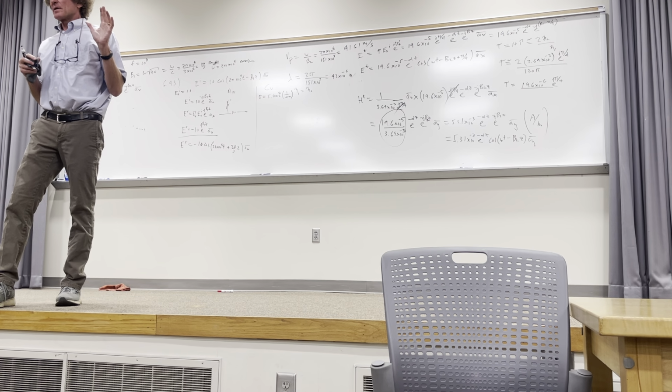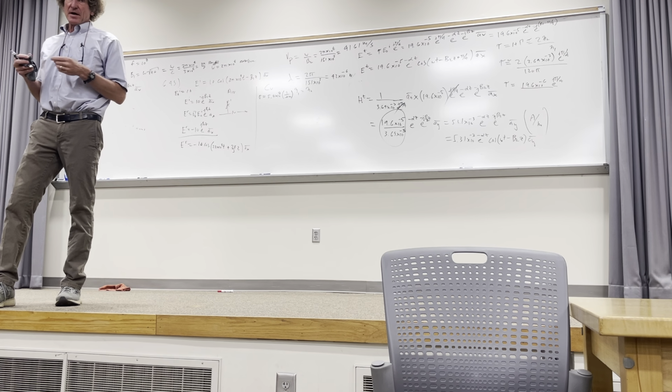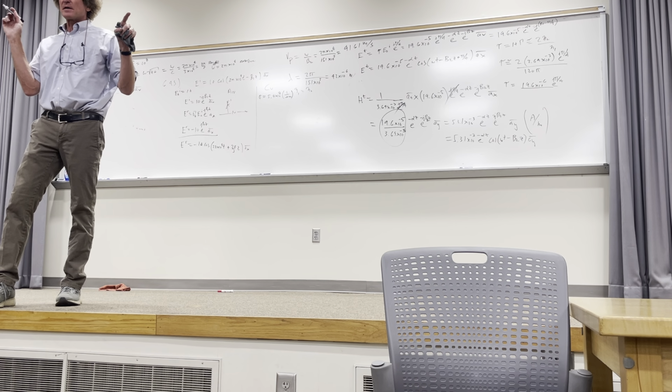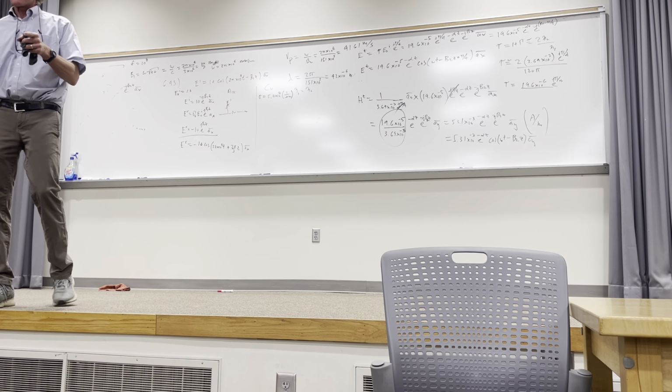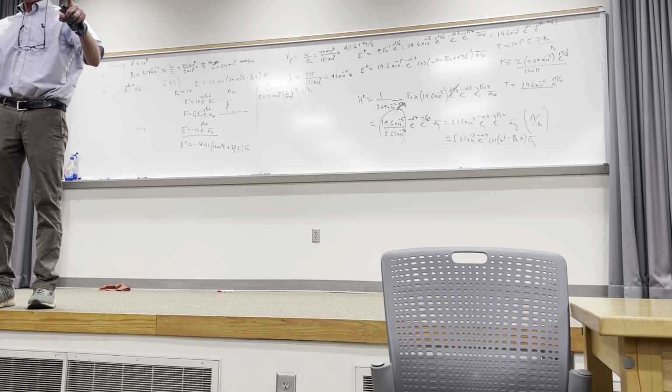We've talked about induced EMF, right? Talked about transformer action, and I'm not going to ask anything about magnetic lifting forces here, so you don't have to worry about that on the final. But we talked about force on both a charge and on a wire segment. Remember my little story about the buried railroad tracks that supposedly were pulled together. That's the way you know. Current in the same direction pulls the wires together, and opposite direction repels them.